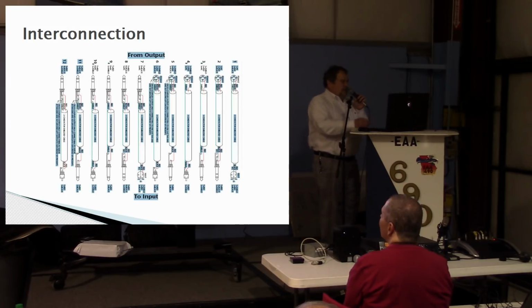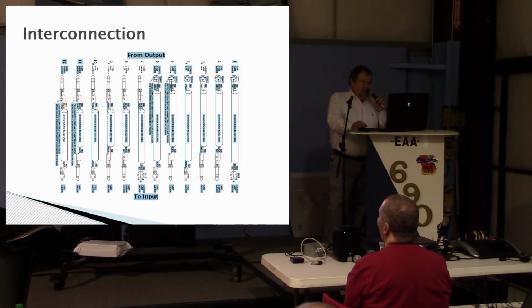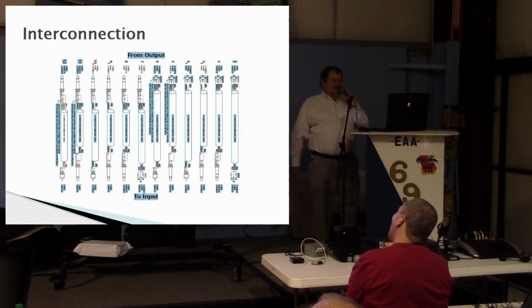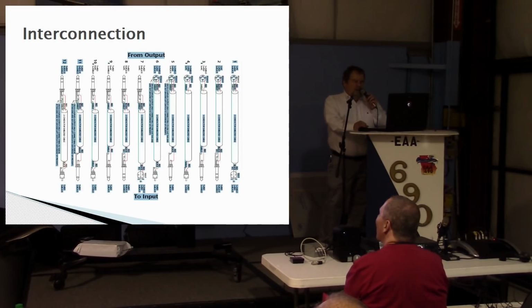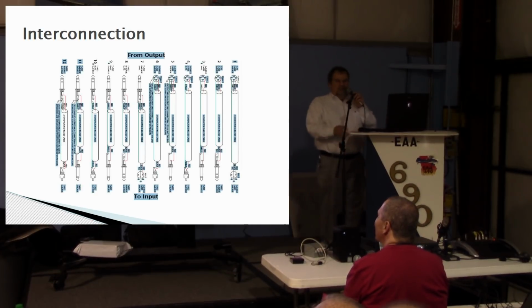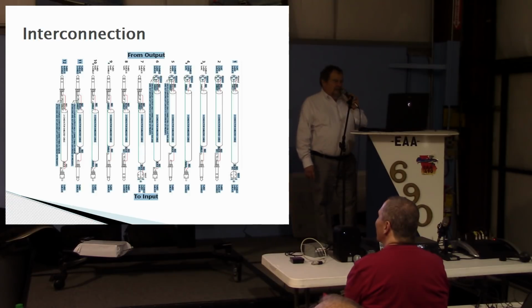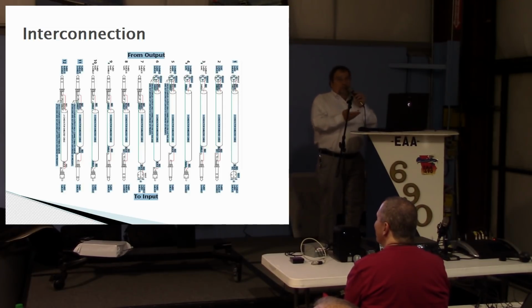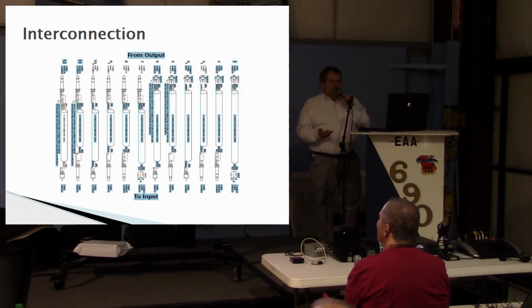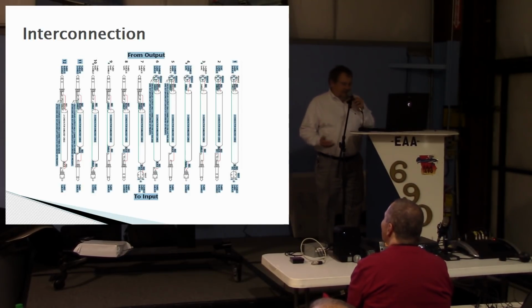Now, quick, take this down so you'll have all this information. This is the different ways you can wire one connector to another. It's absurd, but if you're ever trying to connect a phone balanced to a phone unbalanced, or an XLR to an XLR, a phone unbalanced, Google it. You'll find a chart like this and it'll tell you how to wire it up. That's all I'm going to say about that.